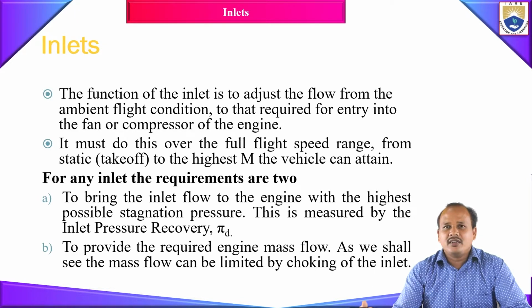So we have different situations, or different flight envelopes, or different operating conditions of our aircraft. Based on that, your inlet also has to adjust according to the flight condition and supply the required amount of mass flow rate at the required speed. That is the purpose of your intake.